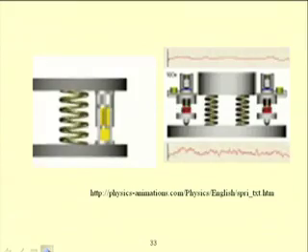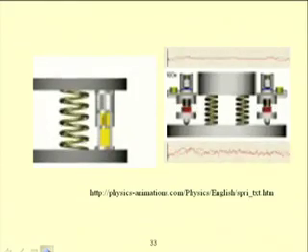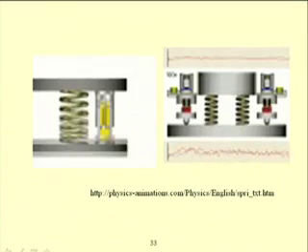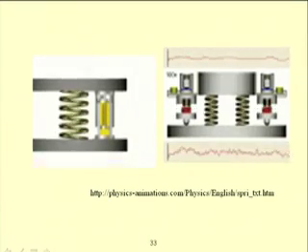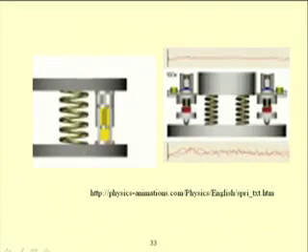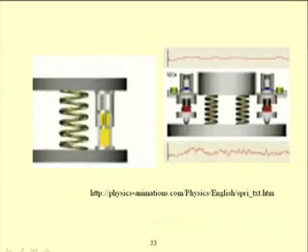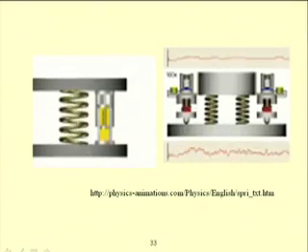Last class we have reviewed some part of the linear system. This is a spring mass damper system. In the spring mass damper system, one can find the equation of motion by finding the potential energy of the spring, the inertia of the mass and the damping energy. The inertia force equals mass into acceleration and it acts in a direction opposite to the direction of acceleration.